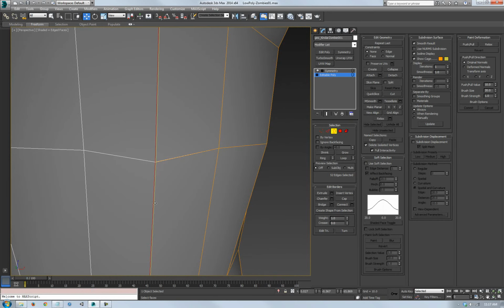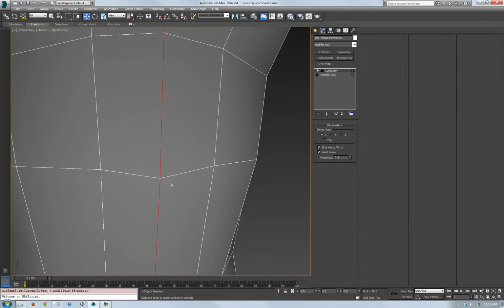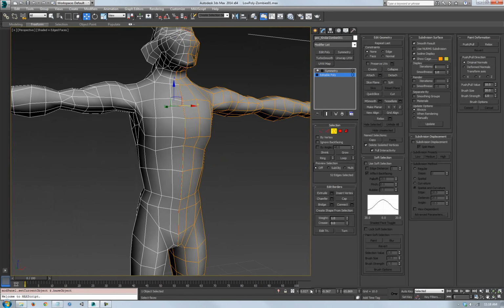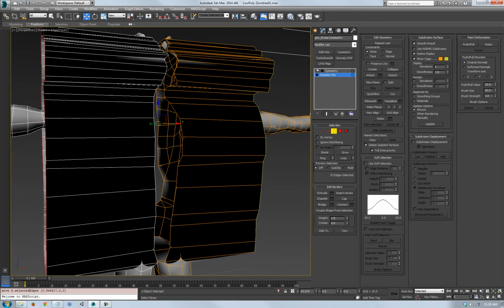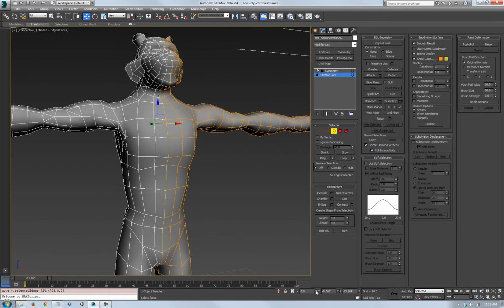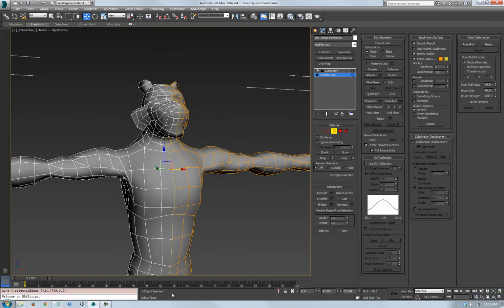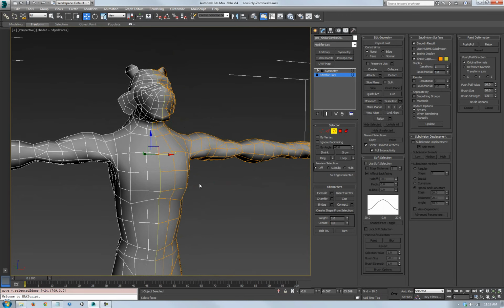As you can see, it's extended over. Now, the symmetry modifier does have an option where you can slice along the mirror, and that's what I've currently got set. But I am finicky. So I'm just going to go into the 0.027, and zero that out. That'll put it right back at the 0 world space in the view. So let's drag that out like that. Again, just right-click, it'll bring it over. And that's usually how I fix up the seam along this, where it's being sliced down the middle. That's how I fix that up.